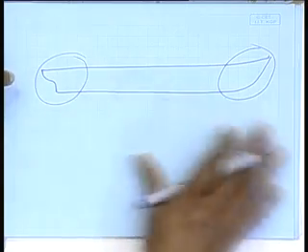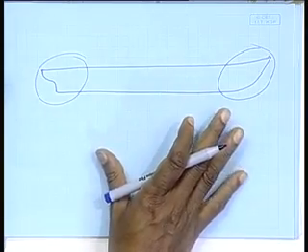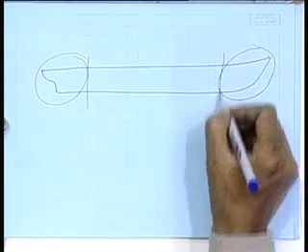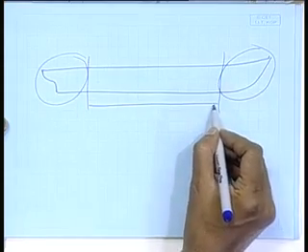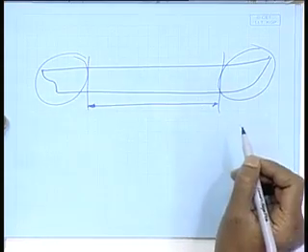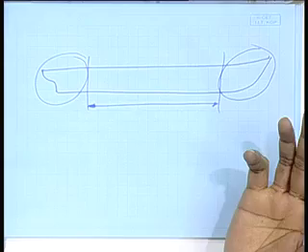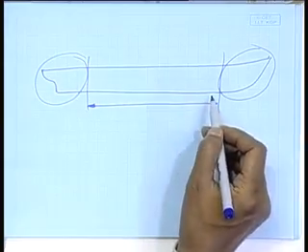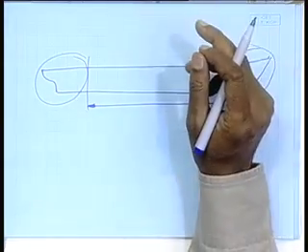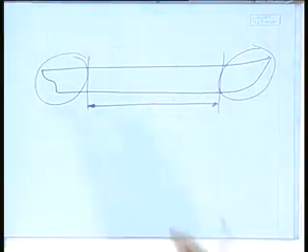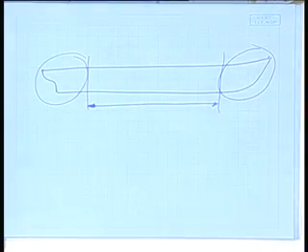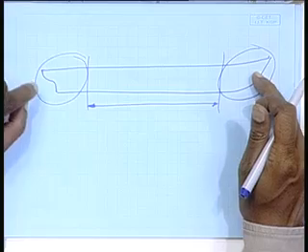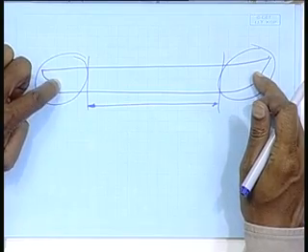What I have drawn is fairly proportionate. So, you can see probably 2/3 or more than 2/3 does not need curved plates. Whatever it needs is in the bilge. For that you do not need such complicated things. A simple rolling machine will do it immediately. That is done very fast. Right. So, only a little amount of curved plates in the forward and in the aft.